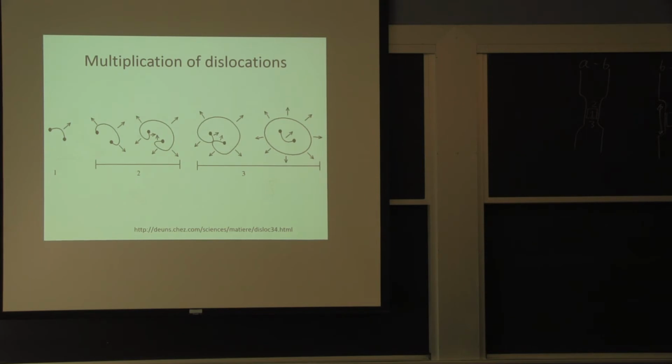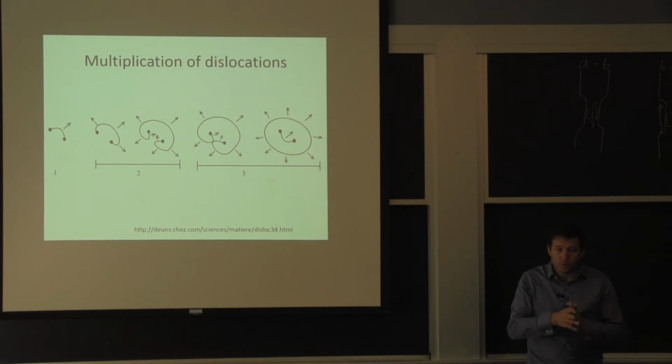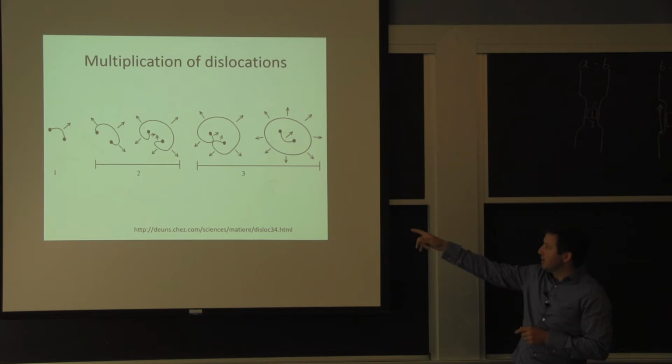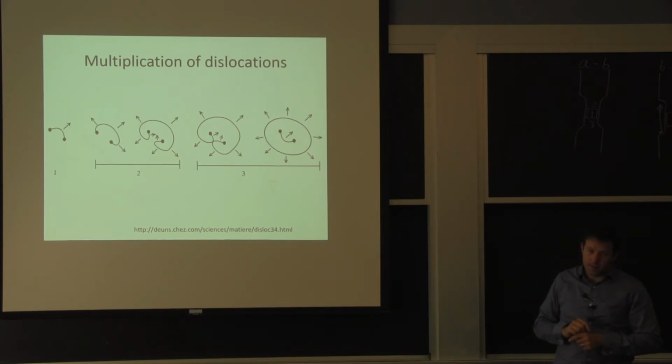The points signify a location where the dislocation is changing orientation completely. So say it was on a certain slip plane and it's going to another slip plane, so it can't really move at that location because it has to move on two planes at the same time. Or, you will see when we talk about strengthening mechanisms, it could be interacting with something else in the microstructure, a little precipitate, that prevents it from moving at that very specific point. The line is the dislocation itself. It's a line defect. Does that answer yours as well?